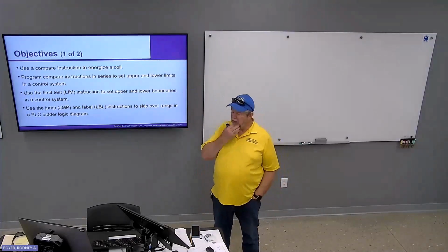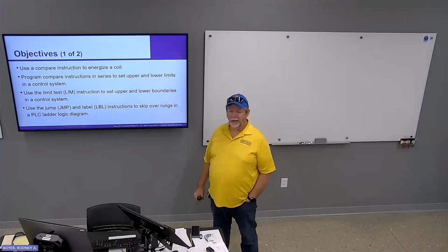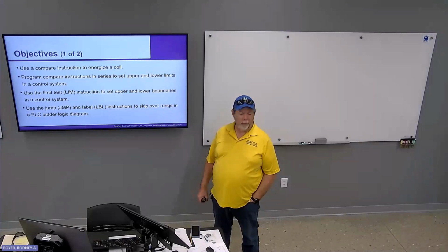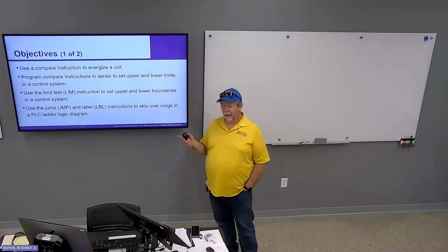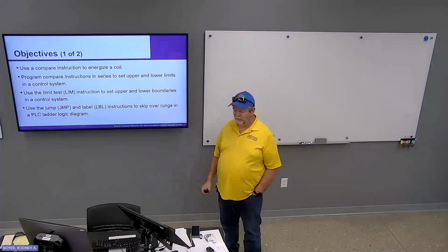Hopefully by the time we get done today, we use a compare instruction to energize a coil. You guys know what compare instructions are? I want to take a wild stab. Comparing two things, exactly. Are they equal? Are they not equal? Is one greater than the other, and so on, right?